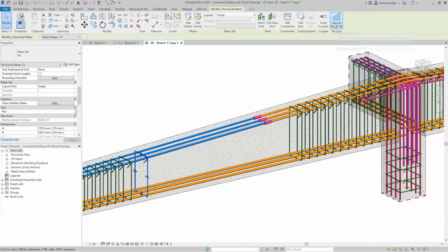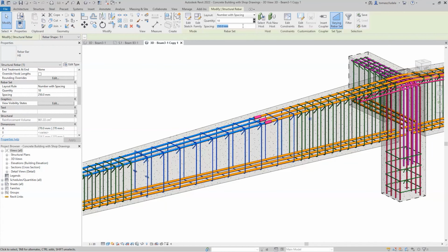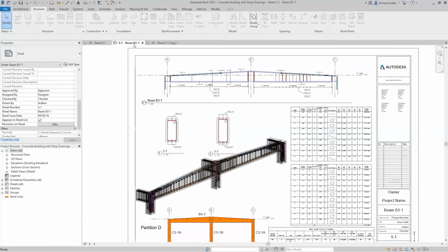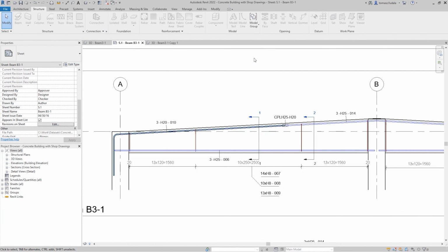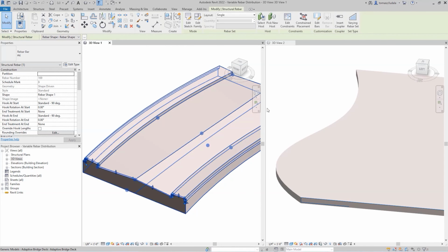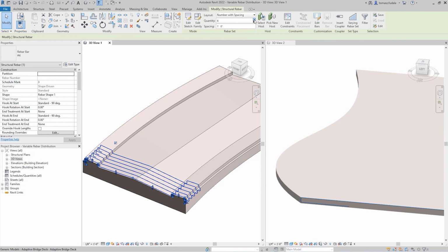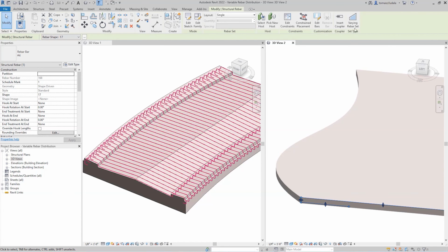Having rebar sets properly defined can help your rebars properly react to concrete geometry design changes. You can define accurate reinforcement for non-standard concrete element shapes by fitting rebar for non-standard geometry with rebar sets that vary along incline faces. Moreover, you can use multi-rebar annotations, customizable numbering settings, and accurate schedules that display varying lengths. The display of varying sets and schedules can be customized by reinforcement settings.